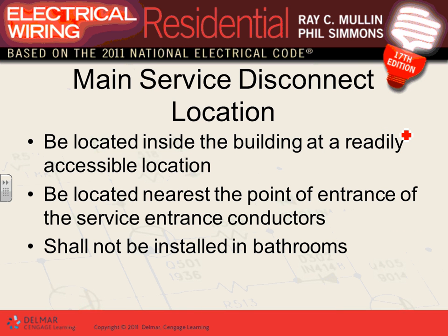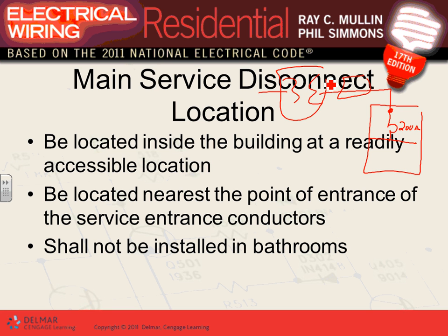Main service disconnect means location. Now, the most important thing, for every service, is a term that's called service disconnect means. Here is the circuit breaker. Can you guys see that? This is the 200 amp circuit breaker. And these are my service conductors coming to the transformer. Here's my meter socket here. And then I'm going all the way to the transformer. Okay? Can you guys see that one?